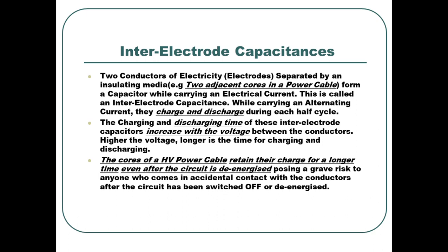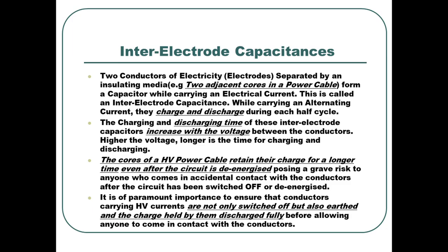The cores of a high voltage power cable retain their charge for a longer time even after the circuit is de-energized, posing a grave risk to anyone who comes in accidental contact with the conductors after the circuit has been switched off or de-energized. So that is the disadvantage. It is of paramount importance to ensure that conductors carrying high voltage currents are not only switched off but also earthed, and the charge held by them discharged fully before allowing anyone to come in contact with the conductors.